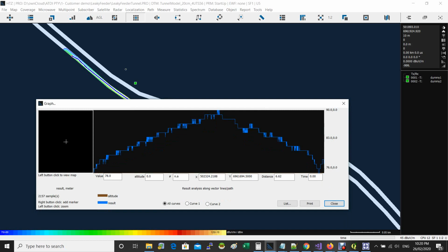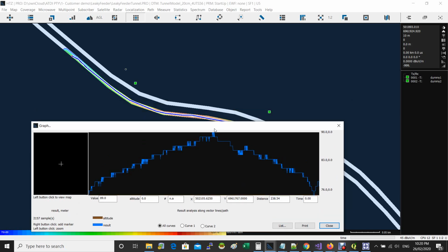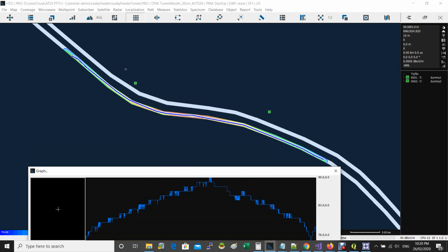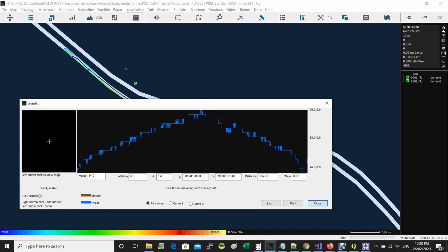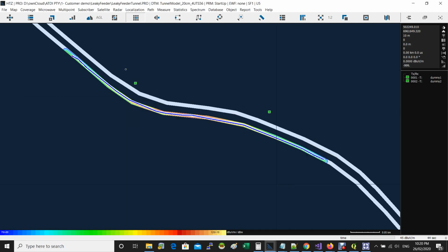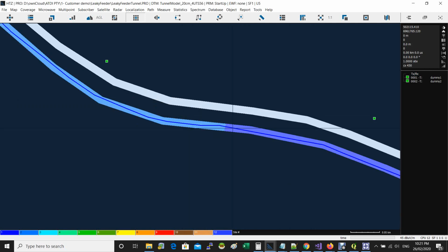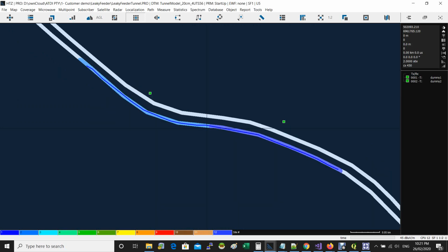So signal was considerably less than the maximum. The signal is enhancing, going up until you reach the middle. Here, that's the feeding point, and then it's going down again. Okay, and you can list these results. You can get them in dBm or something. You can even do Control B here, best server. So you see best server, showing you where is the best server from this or from that, and you can get the signal level for sure.